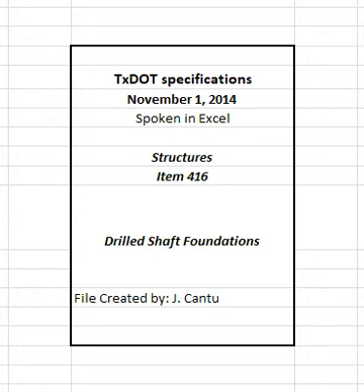The elapsed time from the mixing of the first concrete placed into the cased portion of the shaft until the completion of extraction of the casing must not exceed the time for which the concrete maintains a slump of over 4 inches in accordance with Article 416.2, Materials. Modify the concrete mix, the construction procedures, or both for subsequent shafts if the elapsed time is exceeded. Cure the top surface and treat any construction joint area in accordance with Item 420, Concrete Substructures.